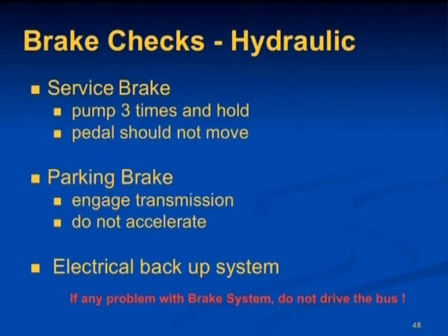The parking brake, again: engage the transmission in a low gear and pull forward against the parking brake to make sure that the parking brake holds. Service brake check, basically the same as with air brakes. Do not wait until you're out on the highway to check the brakes. Test them at a low speed, bringing the bus to a complete stop. Before you leave the transportation facility or your parking area, drive the bus to about 5 miles an hour.